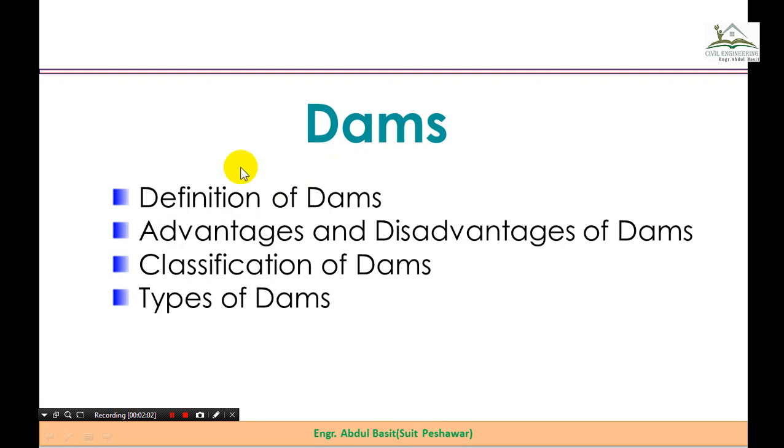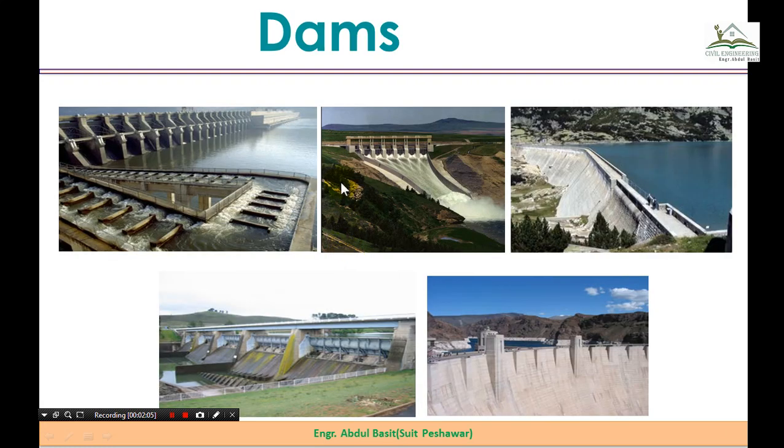Here it is, the dam structures. First of all, the definition. Coming towards the practical view, here we can see a dam structure. On the upstream side, the water is coming in the river, and here is a barrier, a concrete barrier, which consists of two parts. One part is completely solid, and the other part has gates and buffer walls, where we can discharge the stored water in the reservoir on the downstream side. A third part is also located over here, which is the fish ladder.